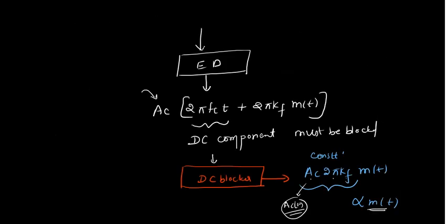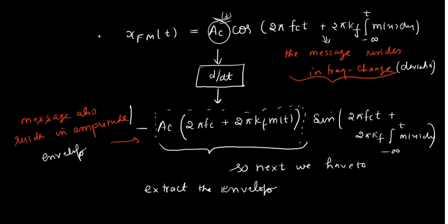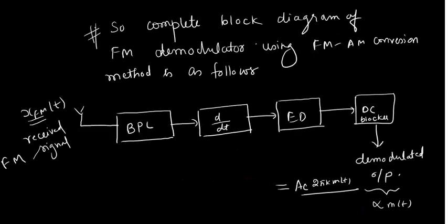But there is one important point which you must remember: in order to perfectly find the magnitude or extract the envelope, we must satisfy the condition that the envelope must always be positive.